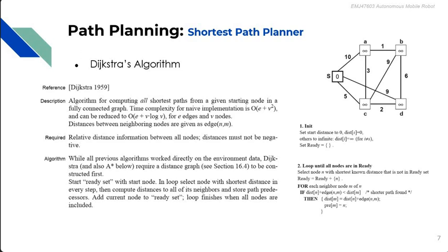With respect to Dijkstra, you don't have that information at all. You just expand in all directions, and at one point you find the shortest distance to the goal. But with A star, you expand in a way that is shortest towards the goal point, right? Because you have the information of the shortest distance between each cell and the goal point. So it will expand in that direction. You don't need to calculate in each direction, only in that direction. So that's why it's more efficient.